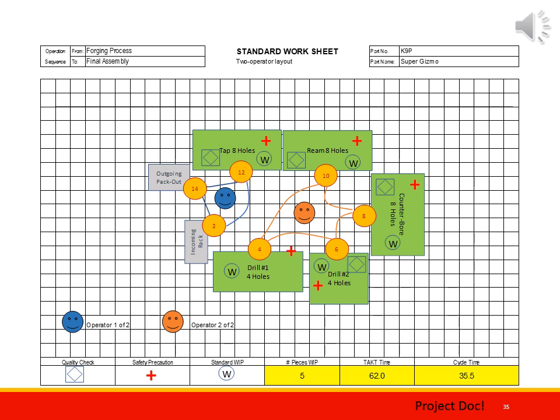You've got to wait for it to auto eject before you can go into the next operation. But if every operation has a part that's already ready and primed, operator 2 can run the rabbit run, right? He can put the part in, hit start, walk over, put the next part in, start, boom, pick them up, all the way around the cell, right? The cell's up and running immediately. Operator 1 is already up and running and ready to put stuff in the pack box. That's called wetting the line with one piece of WIP.